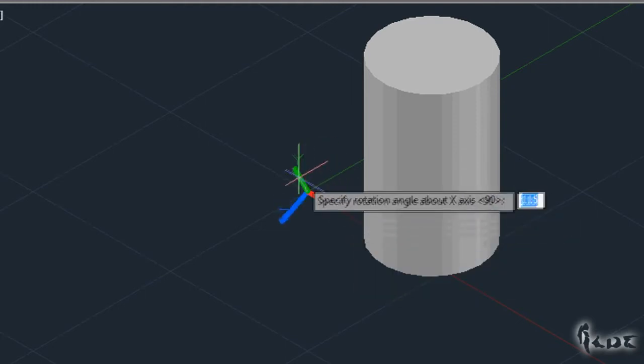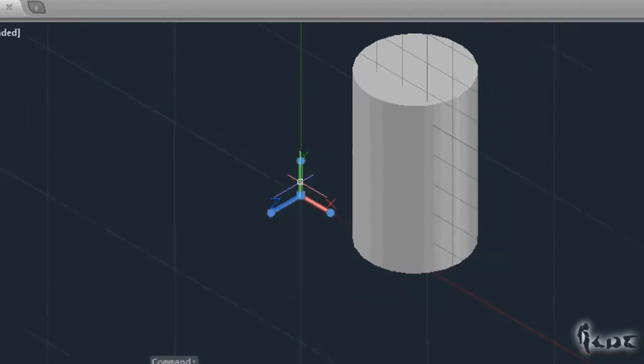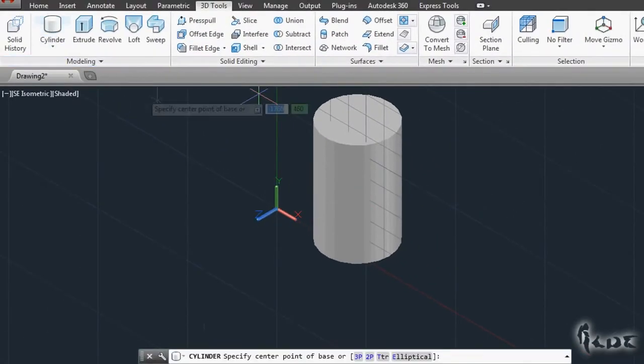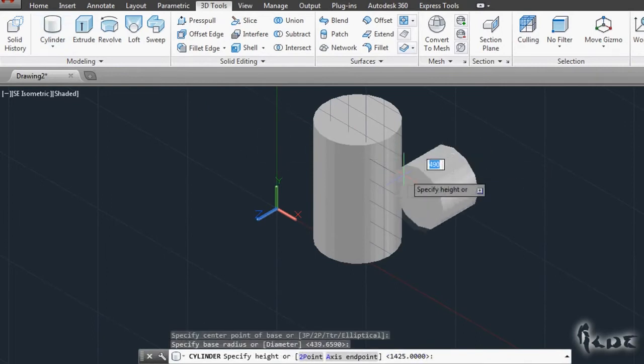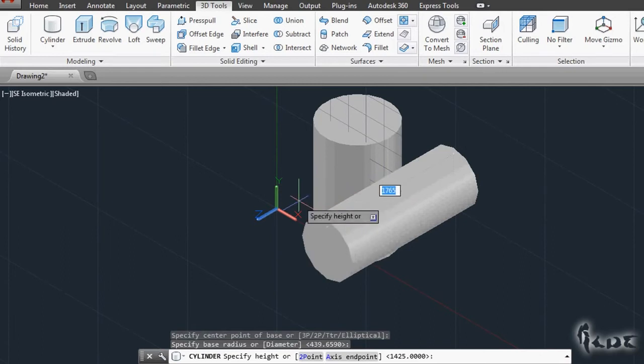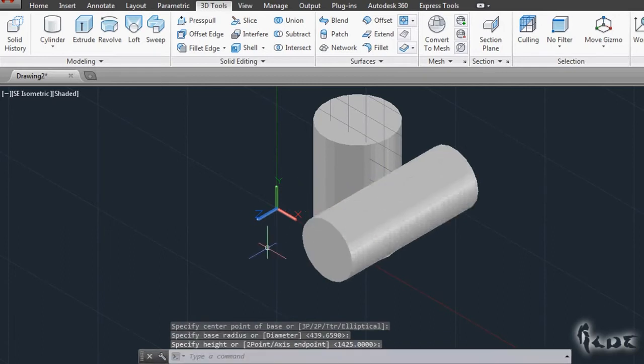This will rotate the workspace, but not the drawings inside. So draw according to this new 2D space and then come back to the original setting. Help yourself with the ortho mode if you want to rotate just 90 degrees or its multiples.